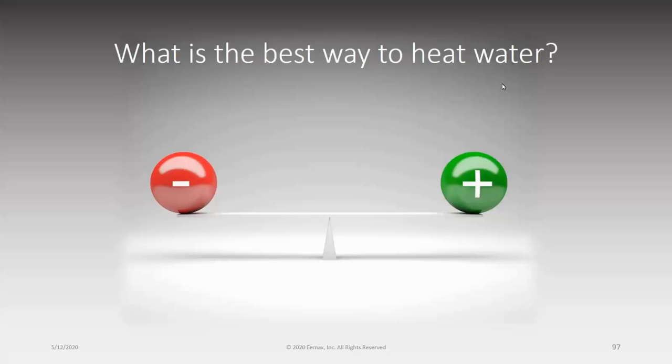So for a hand washing station in New England, at half a gallon per minute, you're looking at a 30 amp circuit. If you did 100 of them, that's 100 30 amp circuits. That may not jive for every project, and if it came in after the fact, they may not have the facility or the support to do it. Maybe the sheetrock was up.